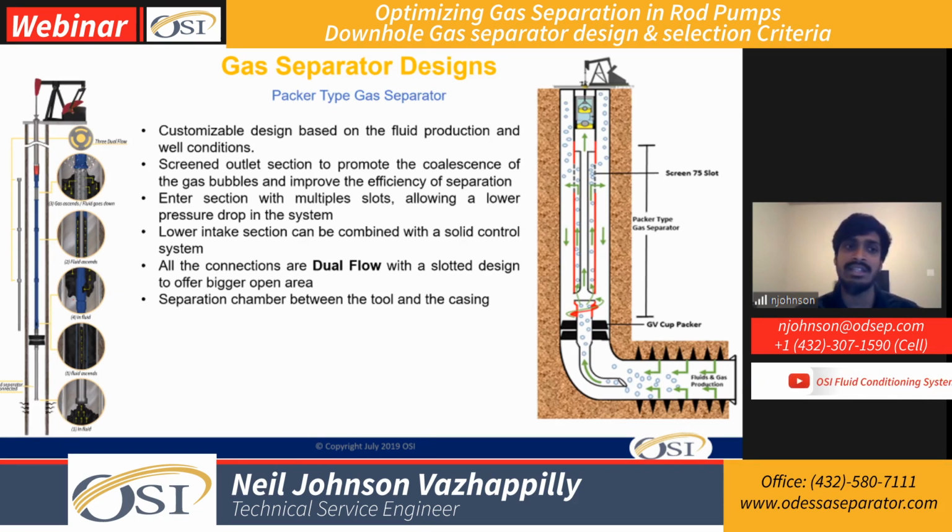But the other section is the joints. In this particular design, we have about 3 joints, 24 foot each, which gets us about 72 feet of total length of gas separator. All of these joints are connected with a dual flow connection, as we can see here on the top section of the left-hand side image.